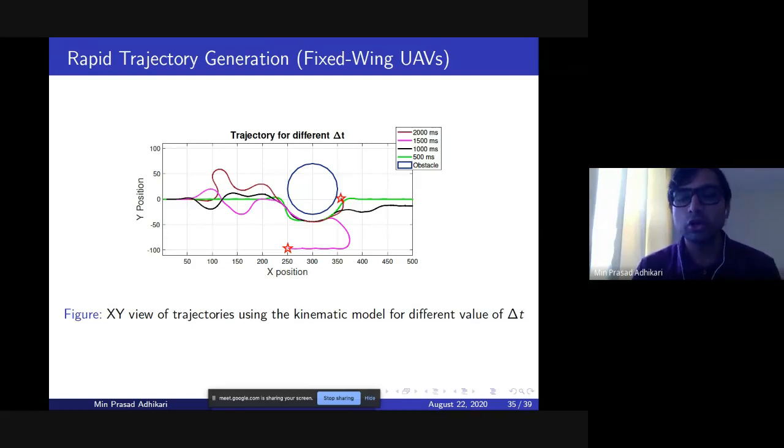The thing is, in model predictive control, let's suppose we are predicting 6 seconds in the future, and we have 20 node points in between this 6 seconds of future time. Let's say we're sampling at 0.2 seconds. We're going to predict the position of the UAV along that time using the UAV dynamic model.